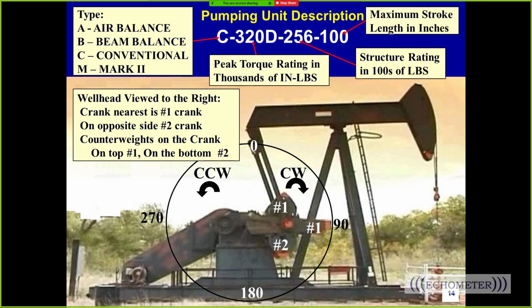Now, for those that haven't talked about clockwise and counterclockwise, when you view the pumping unit from the side, I'm viewing the pumping unit from the side. If I would have put my hand out and the polish rod was in my right hand, then this is clockwise rotation versus counterclockwise rotation. Some people like to say that the crank arm falls toward the wellhead when it's clockwise rotation.